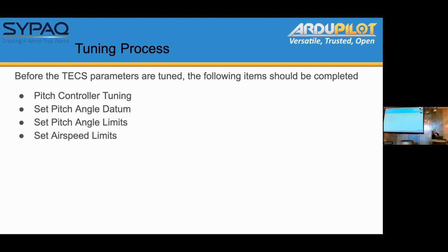What's the pitch angle datum? That's ensuring that if you were to fly in fly-by-wire with a zero pitch demand to the controller, the aircraft would fly and not lose height or gain height. And then there are two methods of achieving that. Then we need to set pitch angle limits to make sure you can't pull up too steep a climb or too steep a descent. And then obviously we need to set appropriate airspeed limits, and that means understanding your stall speed.